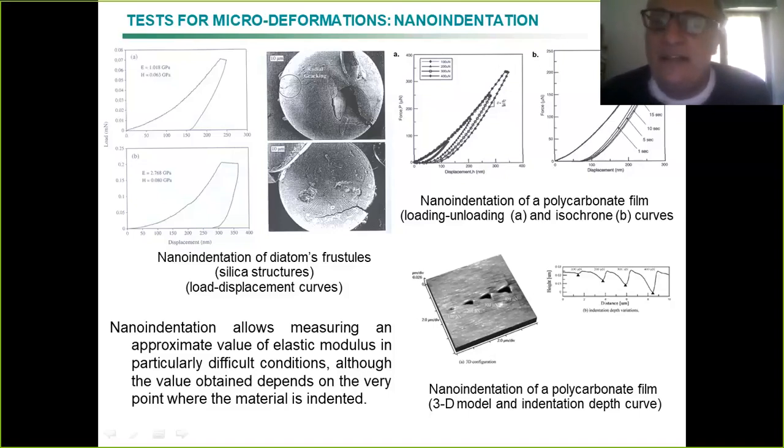In fact, for a ceramic, you usually do bending tests, you don't do tensile tests on ceramic because they have a limited resistance to tensile force, and also because, as a consequence, they are not applied as bearers of tensile force.